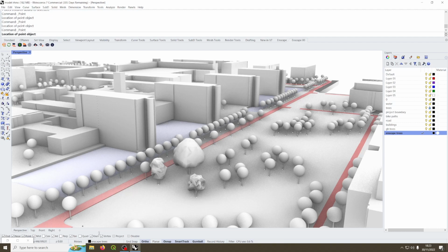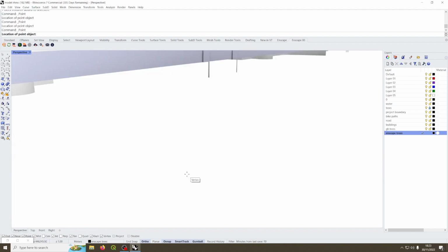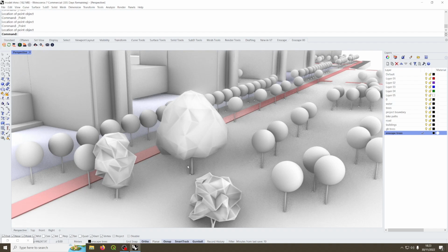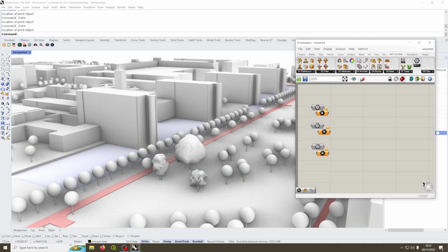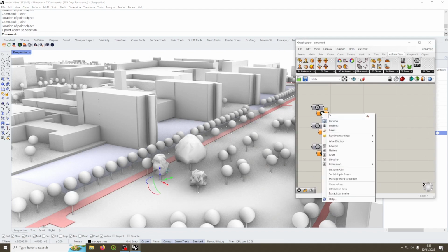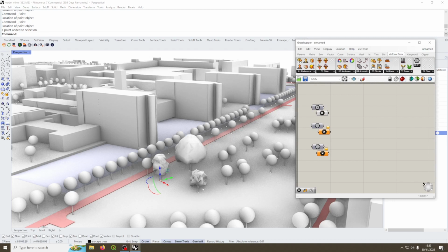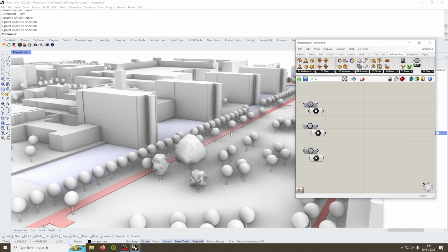Just make sure you have the vertex snap turned on and place the points. So now we'll have to reference those points as well. Click on the first one and right click on the point container. And finally, we need to reference all the points from QGIS.